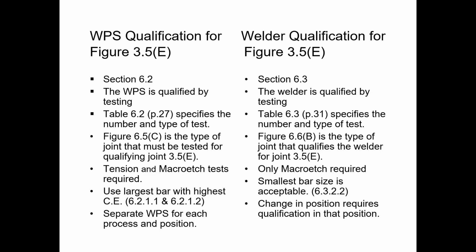Similarly, I won't go through all these point by point, but for the welder, there are similar requirements. The welder has to also be qualified by testing. So they're going to actually do a test weld. Somebody's going to watch them do it. They're going to test the joint, make sure they've done it correctly. There's a specific number and type. And then there's testing that happens on that as well.